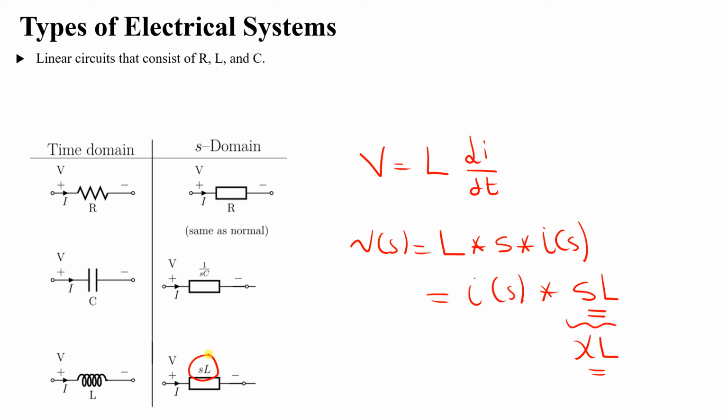SL, as you can see here. Now you will see that in electric circuits again we substitute with J omega L, if you remember from the AC circuits course. Again, why J omega? Because sigma will be 0 in a steady state. Okay, sigma gives us the transient exponential behavior.